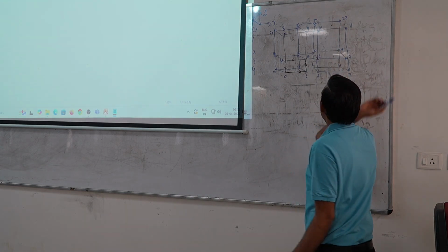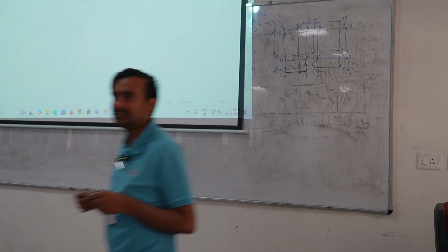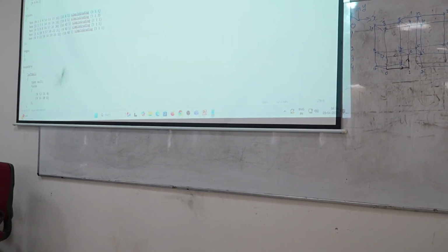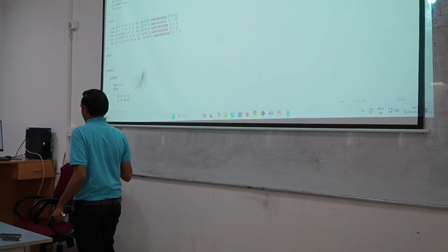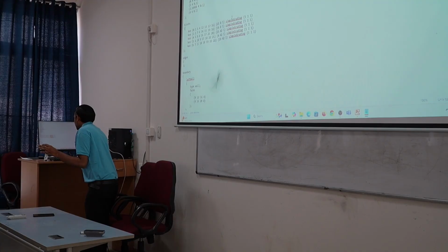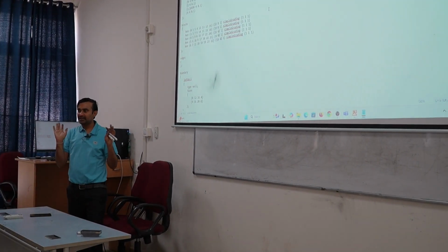I have got the entire domain, all the boxes I have got. Now what I need to do, my geometry is done, I need to define the meshes. When I define the meshes, I need to tell how many elements in each direction. Of course there can be different ways. We are using simple grading over here.